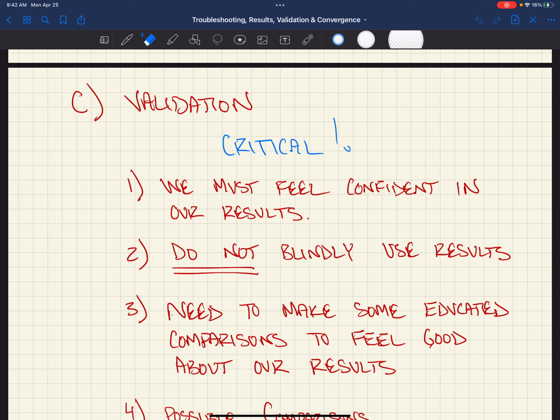You could go to a member, right? A member that you've done simply supported, and you put a uniform load on it, and you could validate that individual member's deflection, individual member's internal forces, right? Moments, shears, and everything for that individual member, at the local level, the micro level, and you use all of these little pieces of validation to validate the entire model as a whole.